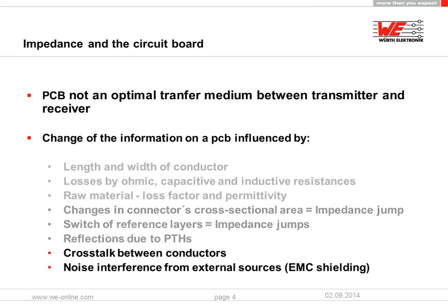We have different possibilities for models we can use in PCB technology dependent on the layer configurations. For example, if we have only one layer available, we have to use surface coplanar construction, or if we have 2 layers available, we can use surface microstrip or embedded microstrip, and strip line needs minimum 3 layers. Regarding the track configurations, we can use single-ended transmission line or differential pair transmission lines.